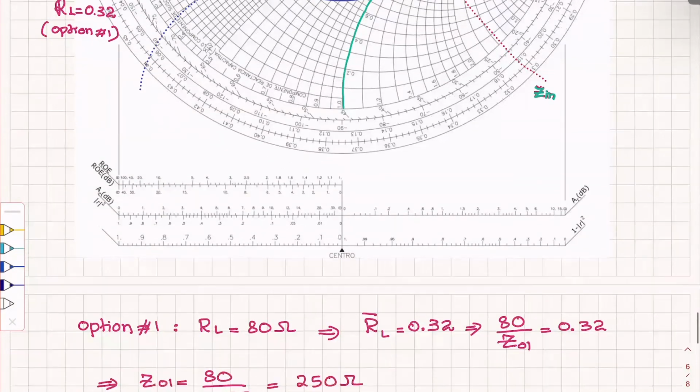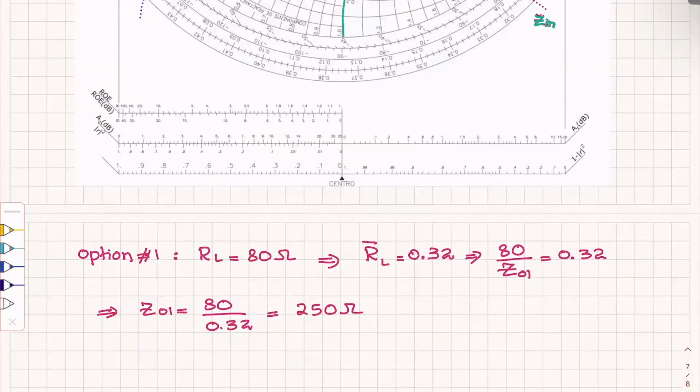Now, if I don't care about doing it in microstrip, I would say, okay, this is one way of doing one characteristic impedance. But if I were to materialize that, I would find that it's going to be very hard on microstrip to realize this. So this is a very high impedance. So I'm telling you, these are the considerations that go into a different design. Theoretically, on paper, you can use it, obviously, and nobody's going to take it wrong. However, if you go to the lab to make a design, that's a very high impedance to realize in microstrip.